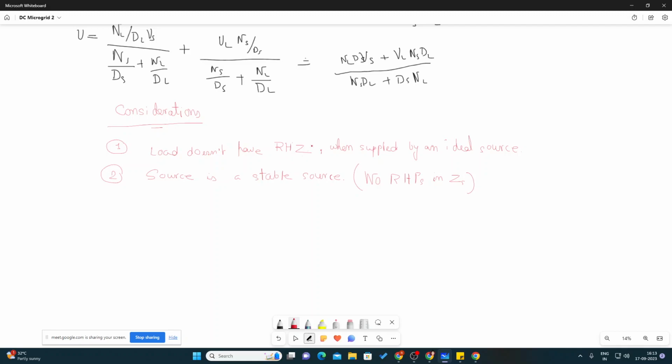If you go through the small signal expressions for buck, boost and buck-boost, buck doesn't have a switching network in between the L and C. The L and C are on one side of the switching network. In the boost, the inductor is on one side and the capacitor is on the other side. Same goes for buck-boost. Hence there is a right half zero.